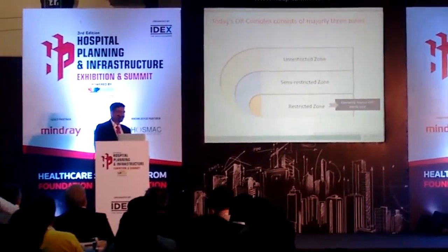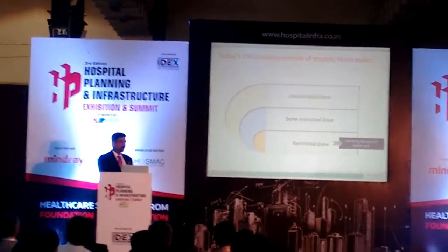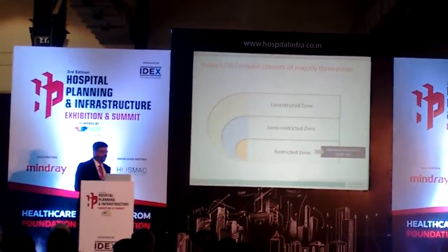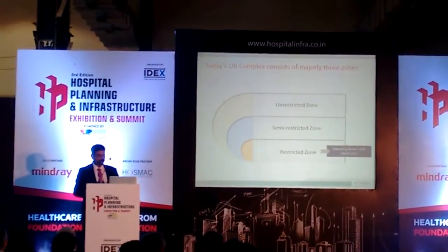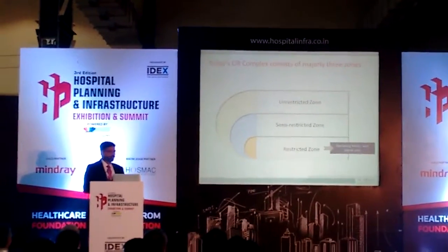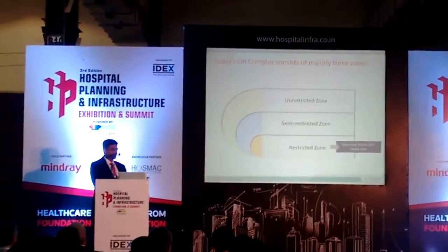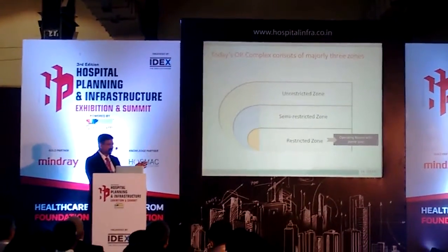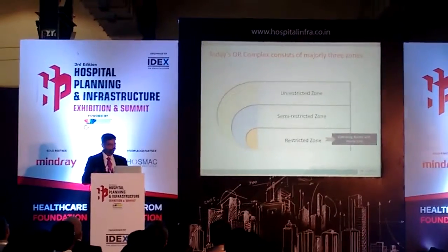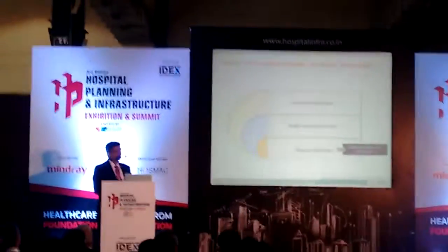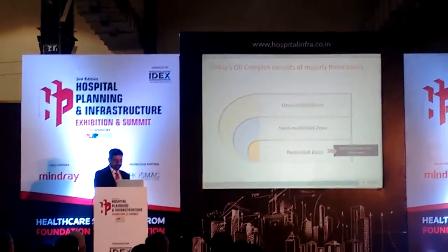This is a drift from the American style of hospitals to an HTM guideline, which is more British. The British had a system of loaded corridors, one a dirty corridor and one a clean corridor, and there used to be a supply. Americans definitely said, no, don't get into all that mess. But finally, when you see these guidelines, the Americans have come back to the HTM guidelines, where you have a sterile core to supply the material into the operating room, and the dirty material can go from the other side.